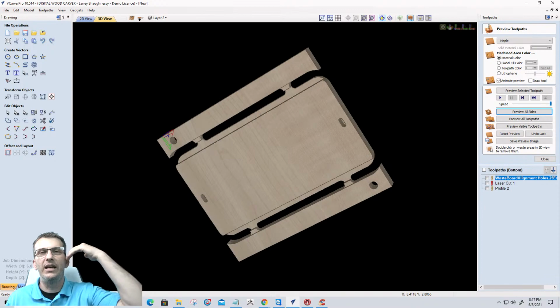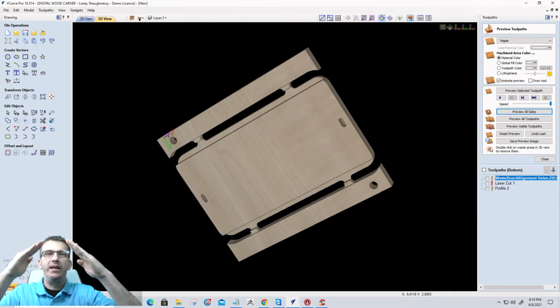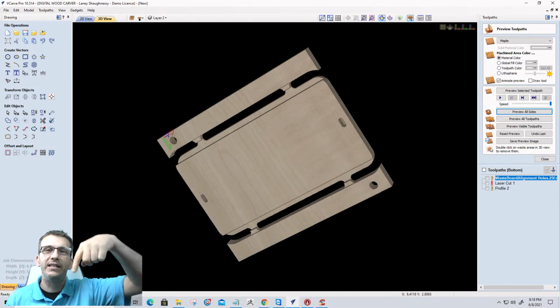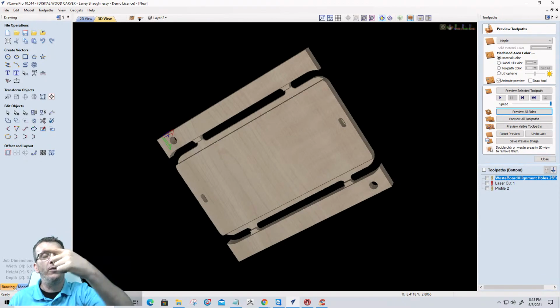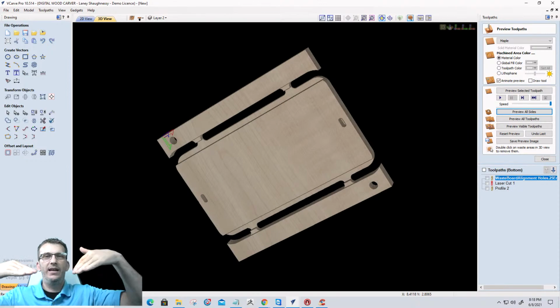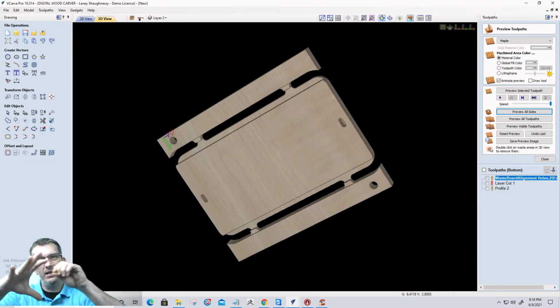And when cutting the base, where we have that dovetail cut, that undercut, now our lid has to have that chamfer, that matching degree angle. We can't cut that on the CNC because the dovetail bit is facing down. If it was facing up in a router table, no problem, but we can't come down. So we're going to have to use a V-bit that matches the angle of our dovetail bit to create our chamfer, or set up a chamfer toolpath in a way that when that lid gets cut with that underside angle, this side angle here, it's going to slide into that dovetail, that locking groove.